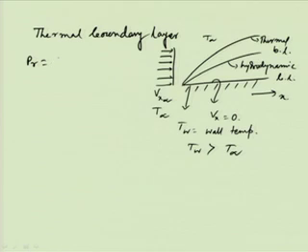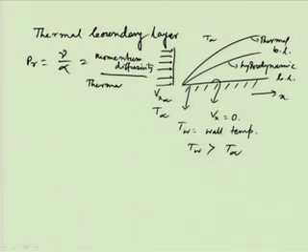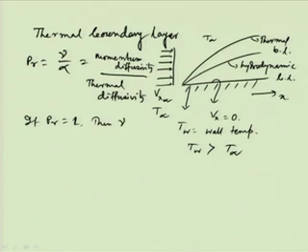So, we know that Prandtl number is equal to nu by alpha. So, it is a ratio of two diffusivities, that is momentum diffusivity by thermal diffusivity. We will see later on that if Prandtl equals 1, then nu is equal to alpha, so both the diffusivity terms are the same. Then we can always say that the two boundary layers will be coinciding with each other.